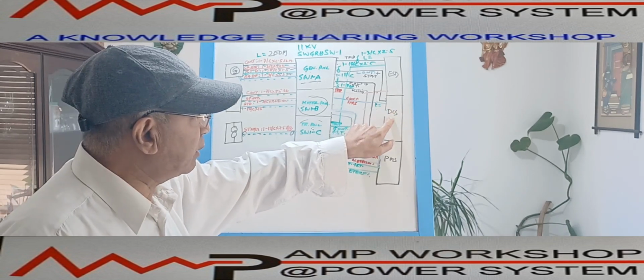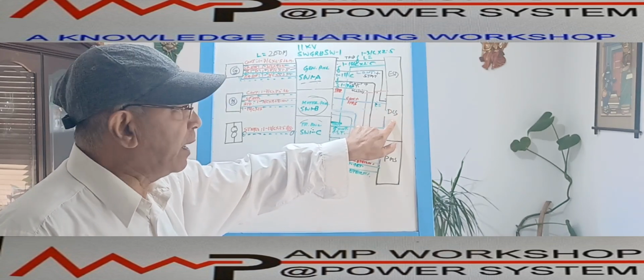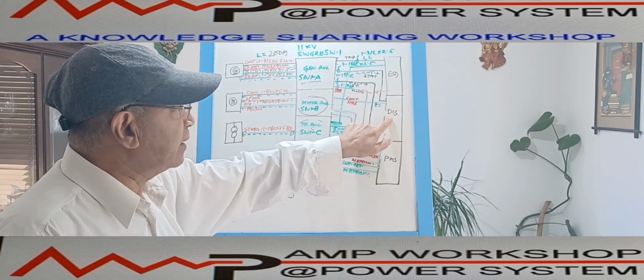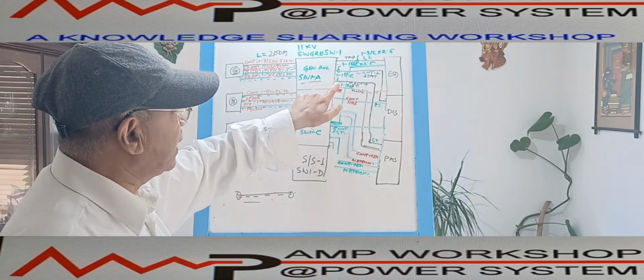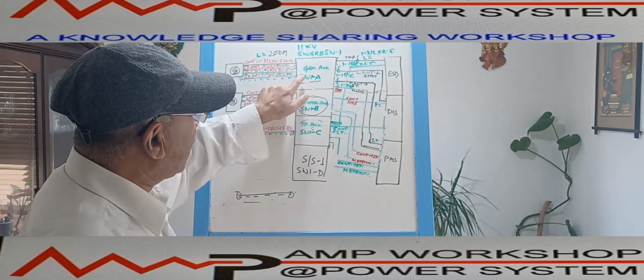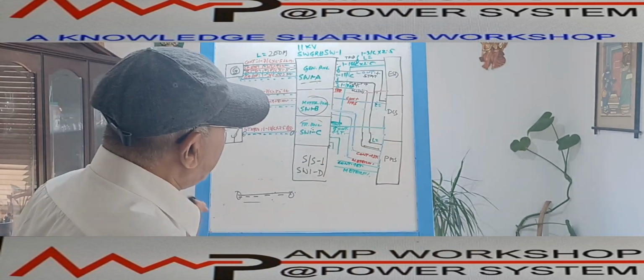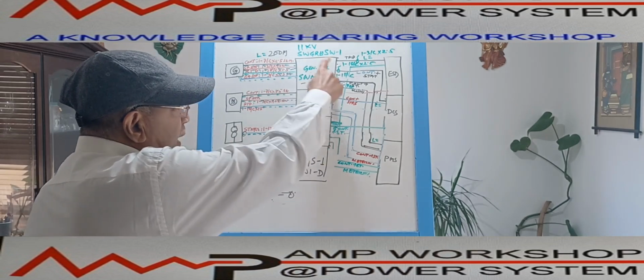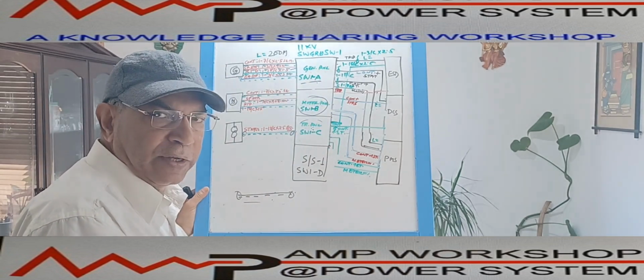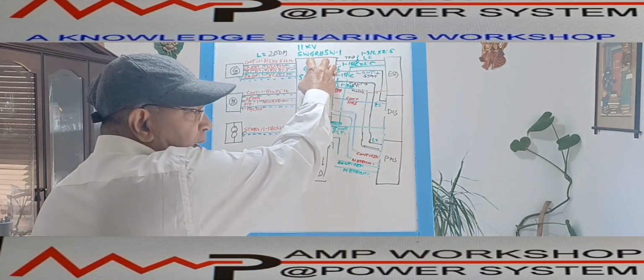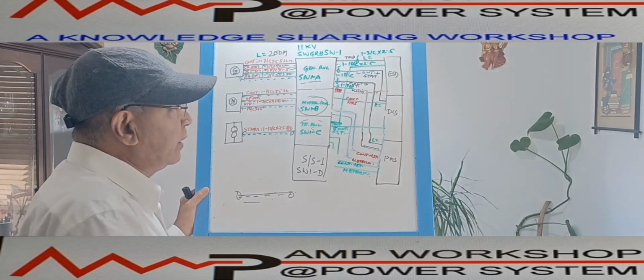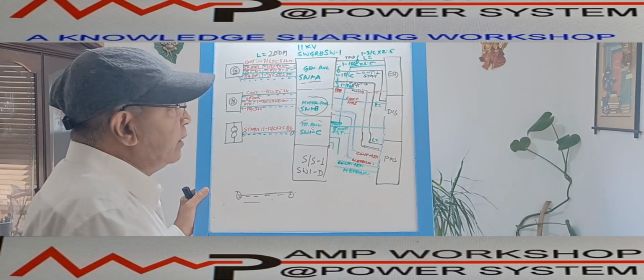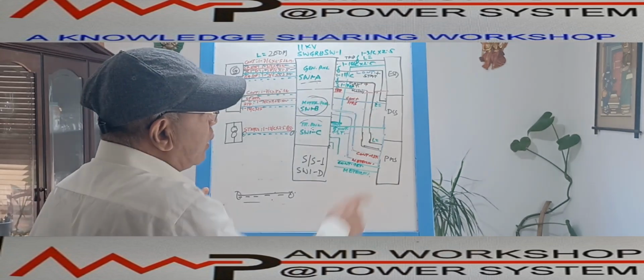So this DCS panel or control panel in the control room has one control plus a status signal coming from the generator panel to over here. Out of that, the status of this generator panel breaker on or off, as well as whether a relay operated or not, the lockout relay operated, that signal will come through a control cable.